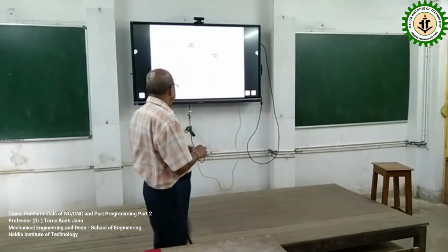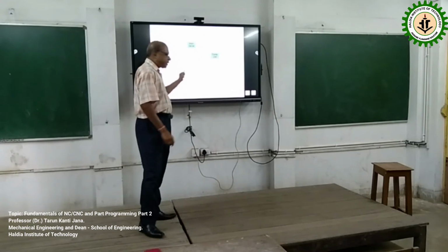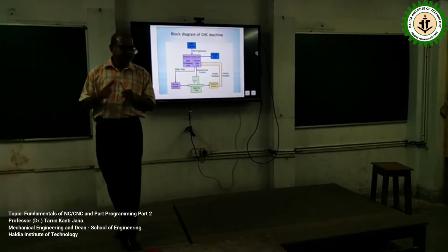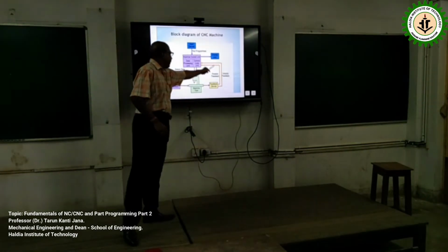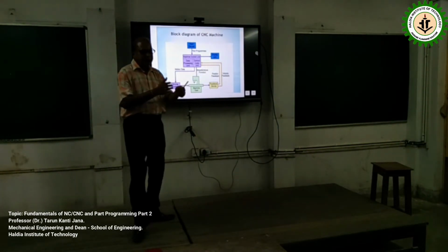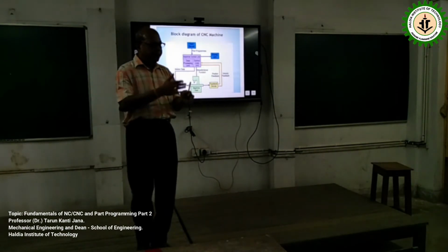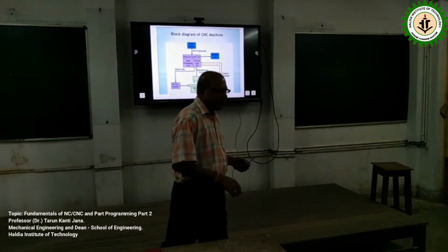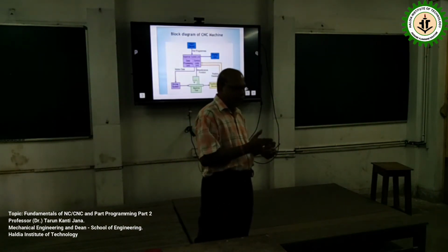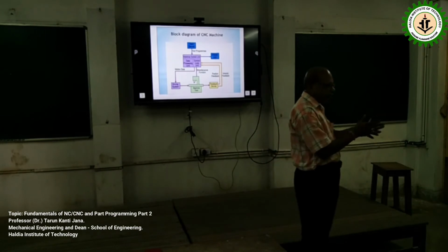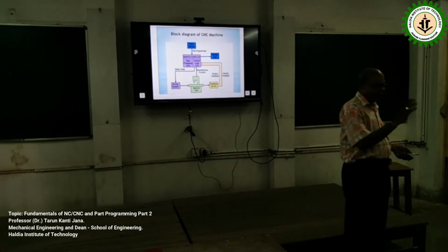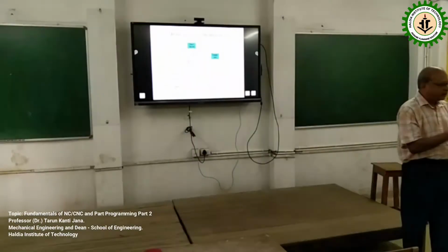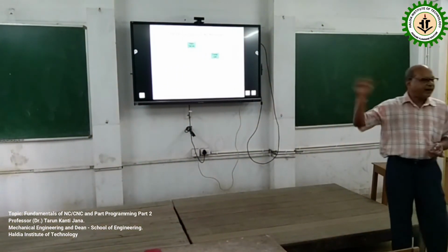So anyway, the principle is basically, once you start moving, this feedback device will start monitoring the velocity and instantaneous position and give feedback to the control loop unit that this much is still left. If you tell me to move by 10 meters, say I have moved by 0.5 meter, that means 9.5 is still due, another 0.5, 9 meters is still due, 1.5 moved, 8.5 is still due. That means continuous feedback of how much is left, and this is popularly known as the error signal.